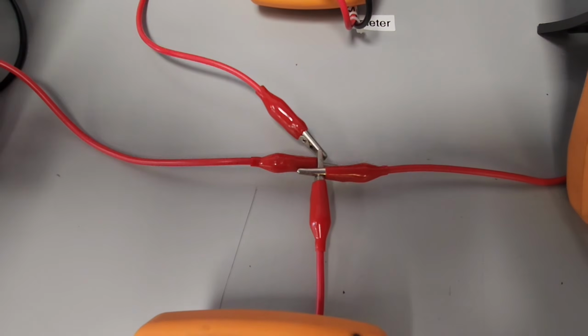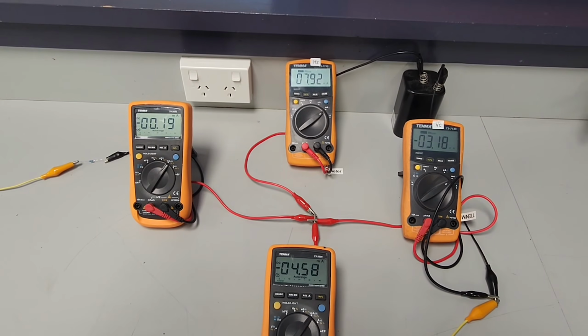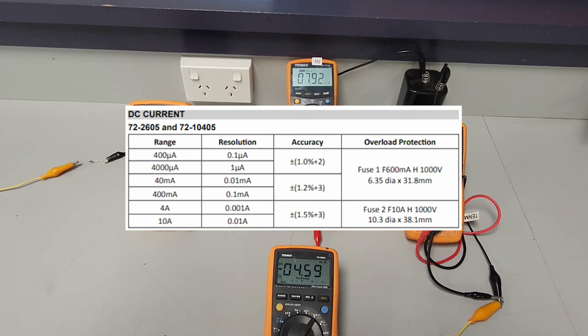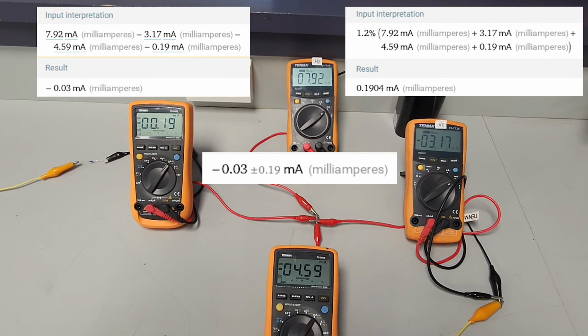This is really just another statement of conservation of energy. Here I have a 4-way junction with multimeters displaying the current through each branch. Kirchhoff's current law tells us that the sum of these currents should equal 0. For DC current, these multimeters measure to an accuracy of 1.2%. Adding the currents and their uncertainties gives a total current of negative 0.03 plus or minus 0.19 milliamps, which with an uncertainty is effectively 0.